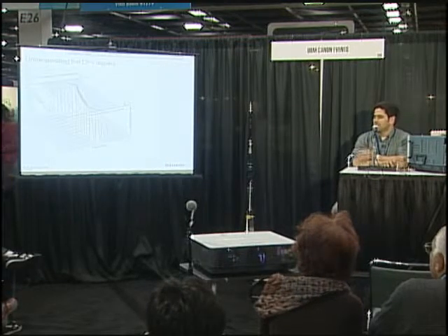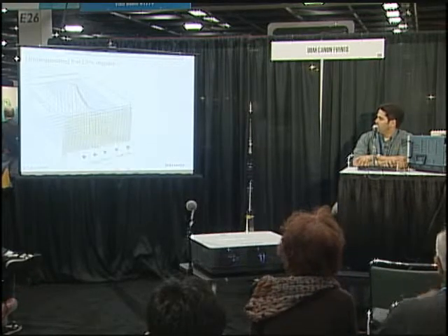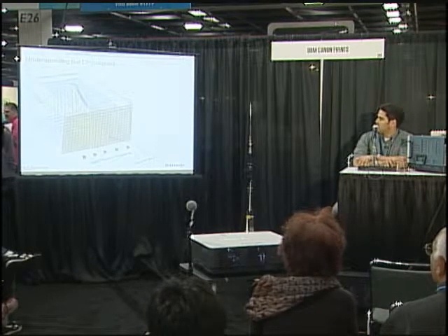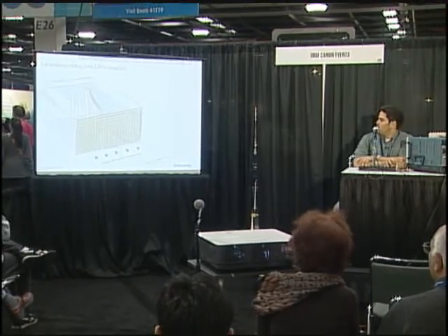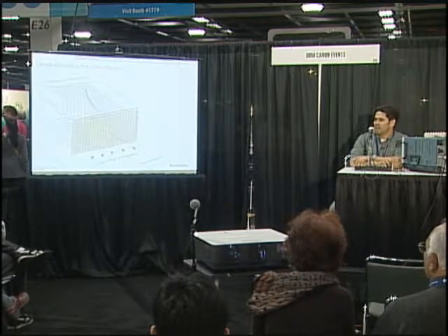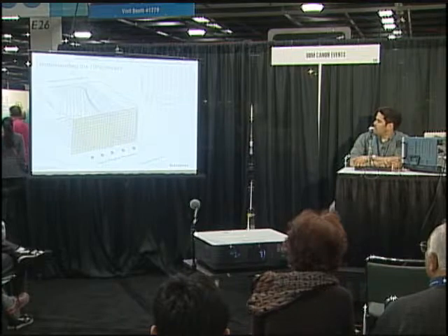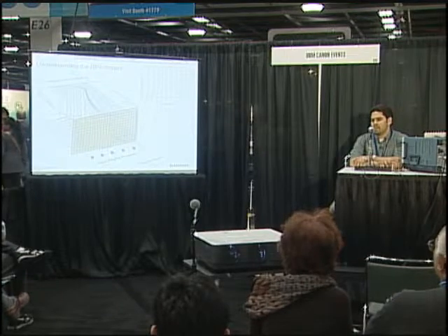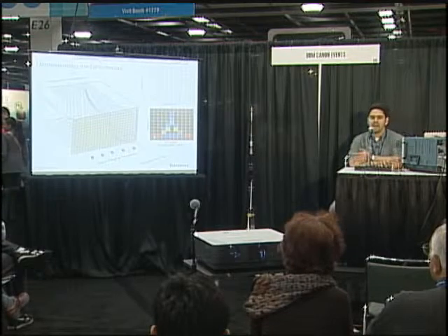The way we build the DPX display is, using the same example as we did before with the spectrogram, now, instead of looking at the signal from the top, we look at it from the front, right? And then we pixelate this plane, and then we just count how many hits are per pixel. So, for example here, this little transient had 2 hits. Maybe if we look over here, we'll find like 7 or 10 hits because there's more activity there. So we end up with a bitmap like this, with a hit count per pixel. And then we color grade, and wherever the number is high, we get red.